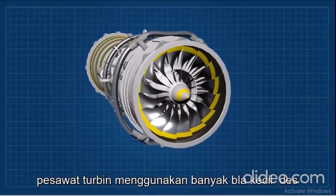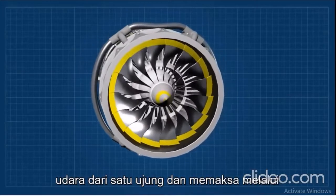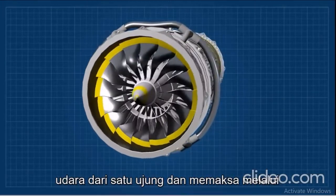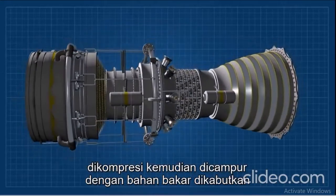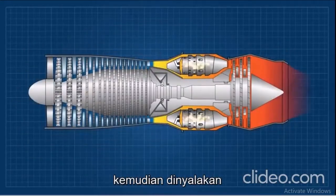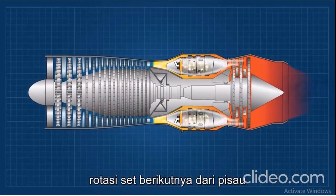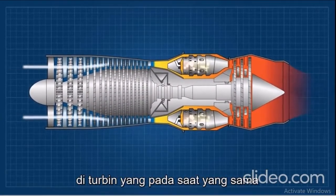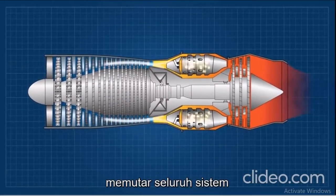The turbine uses a lot of small blades rotating at high speed. The engine takes air from one end and forces it through the different stages where it is compressed, then mixed with atomized fuel, then ignited. Then the expansion of the gases will escape towards the back, forcing the rotation of the next set of blades in the turbine, which at the same time turns the whole system.